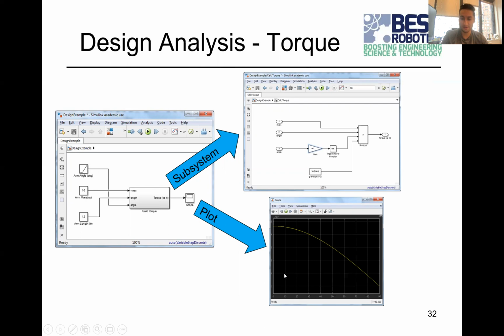You can find the sensitivity charts. Like the torque drop is smallest in this first part, from 0 to 10 degrees of angle. So maybe you want to design your robot around that. That's the engineering design process that is followed in industry, and that's why this is so powerful.